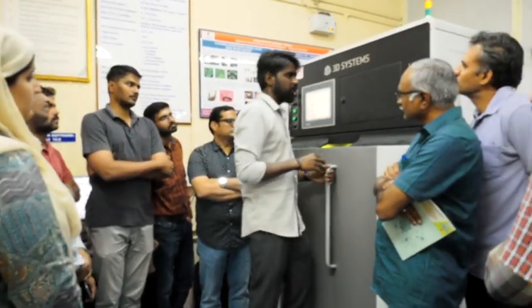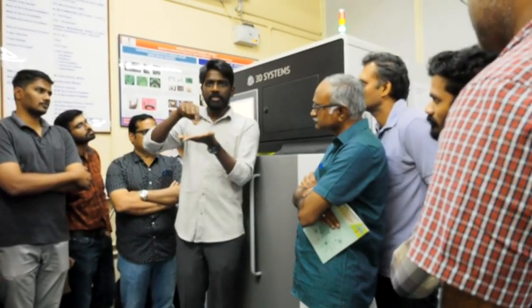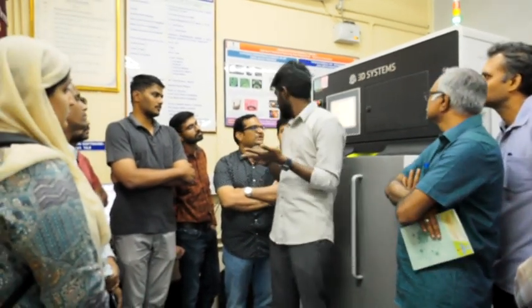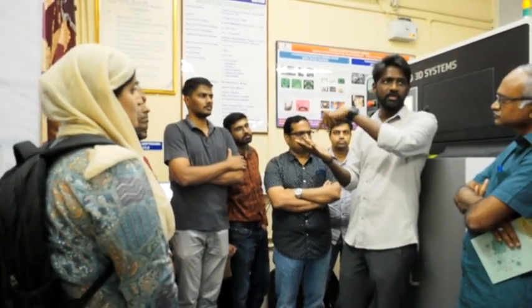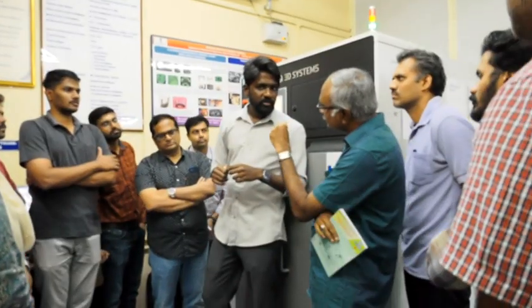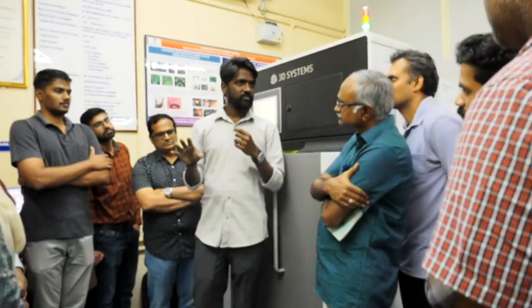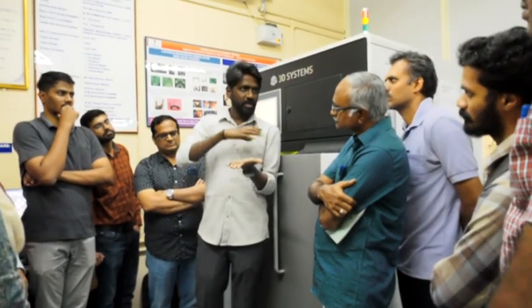I think you have already seen some videos regarding how the laser melts the powder particles. Before lunch, I already showed you that single-layer sintering process. One layer is spread, followed by the sintering process, and then the roller spreads the powder again for the second layer. So what is the thickness? You are controlling the thickness of the powder? Yes sir, right now the powder particle size is 45 microns, but the layer thickness will be around 30 microns. So up to 30 microns you have to melt the powder.